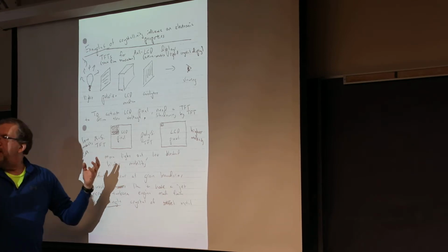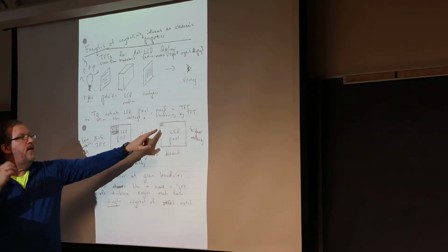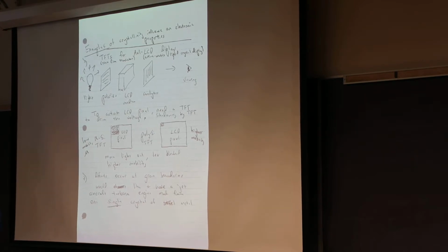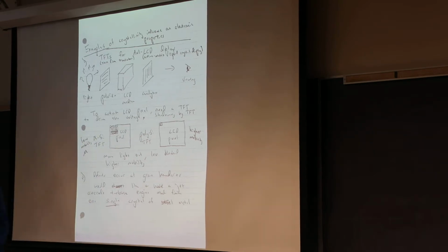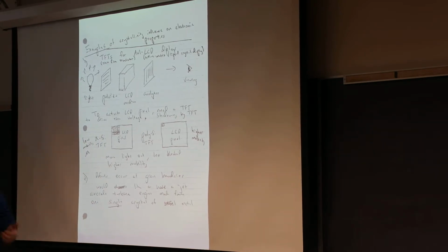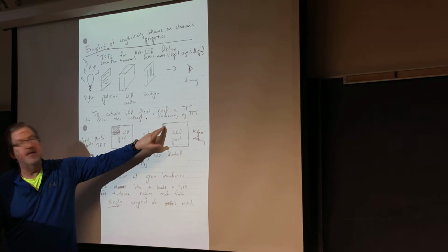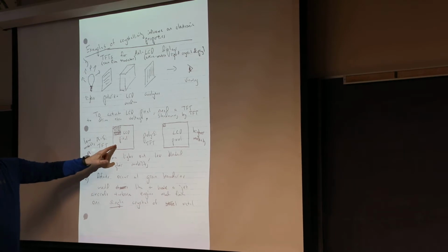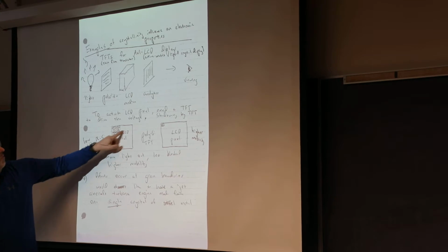And somehow with a very high speed laser, they were able to heat up the silicon and make it melt and then recrystallize slowly so that it could become more polycrystalline, and then the mobility goes up, right? Because the greater the crystallinity, the less scattering. So you're able to make the transistor driving that pixel smaller because the mobility goes up, and therefore that pixel allows more light through, right? Because this is where the light goes through.